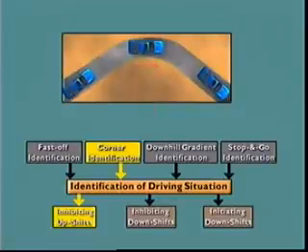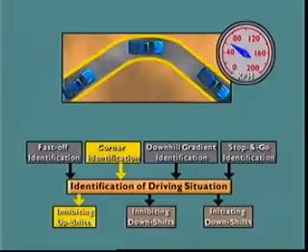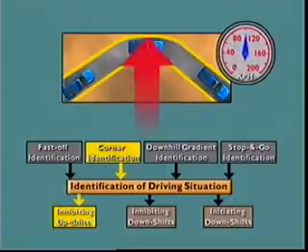The radius of the curve is determined by comparing the rotating speeds of the inner and outer front wheels when the vehicle is not traveling in a straight line. This data from the wheel sensors, added to road speed, allows a sufficiently accurate estimate of lateral acceleration. If corners are taken at a particularly high rate of lateral acceleration, downshifts are also inhibited.